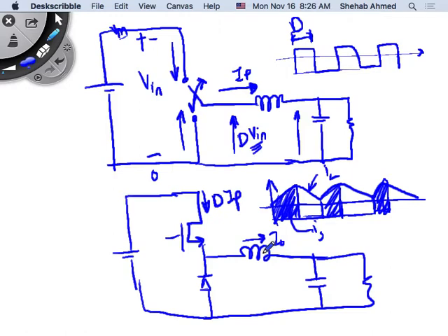With this combination of components, you were able to come up with the Laplace equivalent circuit. Basically, you wrote the equation of the Kirchhoff voltage law in the Laplace domain, and you came up with a Laplace domain representation of Kirchhoff voltage law for the circuit, right? And there, for example, you were able to relate the input voltage to the inductor current. You had a relationship where it was V input over S, right?